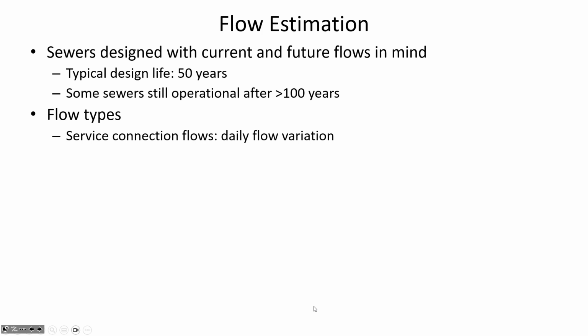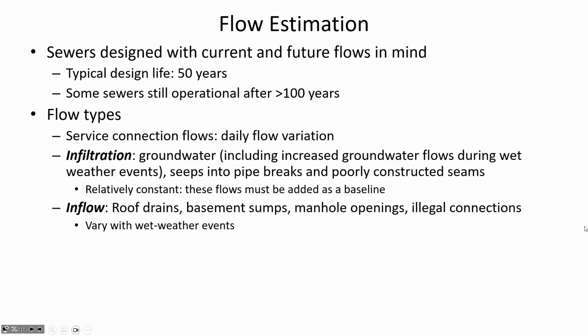So that's the water going to the house. It's going to be more in the evening, for example, than it is overnight. But then think about the water that comes to the house. A fraction of that is going to end up in the sewer. Most of it, actually, is going to end up in the sewer. And so if people are using a lot of water at 7 or 8 p.m. as they're washing dishes, taking showers, cleaning, and so on, a lot of that's going to be getting into the sewer, but then the flows are really low overnight. So there's a big variation in flow, and there's different empirical equations that have been developed in order to try and speculate on the ratio of low flow to average flow, and to speculate on the ratio of peak flow to the average daily flows.